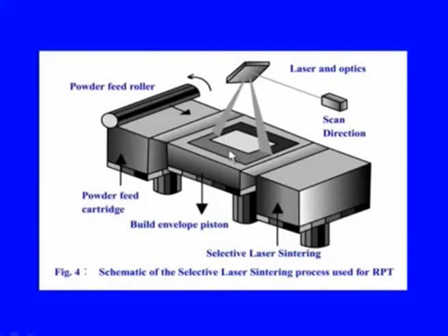One thing to be remembered here, as we have seen in the previous figure on the screen, is that this entire area of powder need not be fused by sintering, by applying this laser. Say for example, here it is a kind of square ring. In this area only the laser is allowed to fall, and this area only will get melted and bonded to the previous layer,